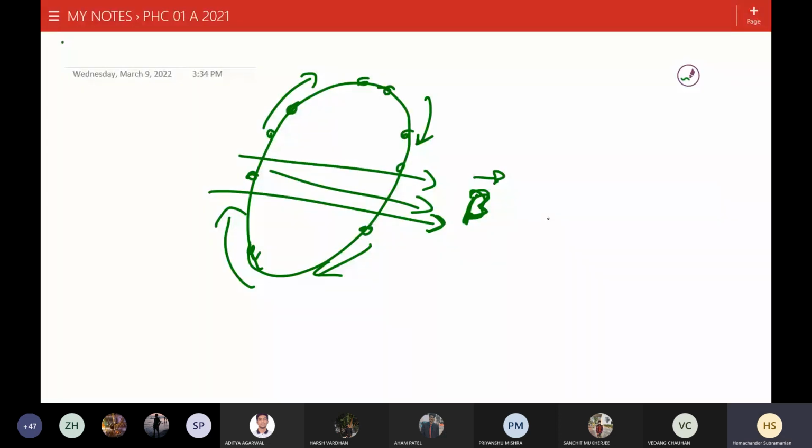Okay, when you change the flux, the electrons are going to move. That's basically your electric generator. That's what the generator does. What does an electric generator do? It moves the magnets, and the magnetic flux changes, and that change in the magnetic flux creates an electric voltage across coils wrapped around the magnets. This is exactly what is going on in the generator, right?